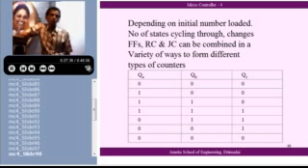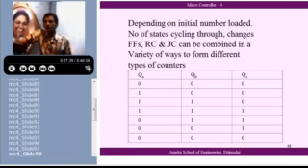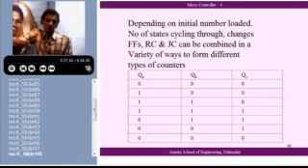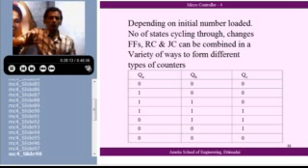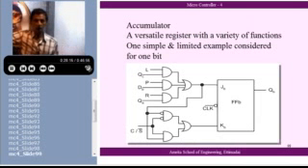Wherever you have a batch process where I want 2, 3, 4 sets of activities to be done in a sequence, perhaps a ring counter will be a direct application. In that sequence, when it is in one state, I would like to switch on 2, 3 switches. Next state, another set of switches. A ring counter may be the simplest thing to be used there. I can use a binary counter and do that, but a ring counter may be the simplest one to be used. Coding you can do that, directly you can do that. Essentially, it's like a binary counter with a built-in decoder.